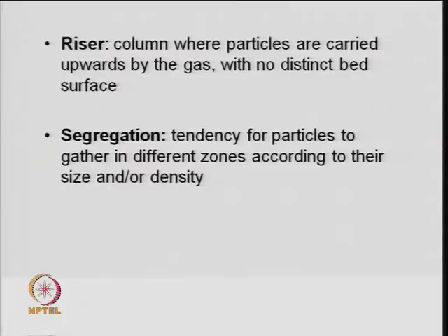And segregation is another term, which defines the tendency of particles to gather in different zones according to their size and density, as I was discussing with the Geldart chart. There will be lumps of particles at localized places in the bed column, and the gas will channel. This is not a desired condition when you look at a good fluid bed reactor design.